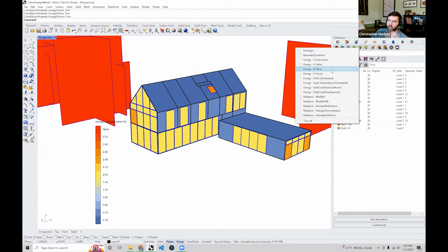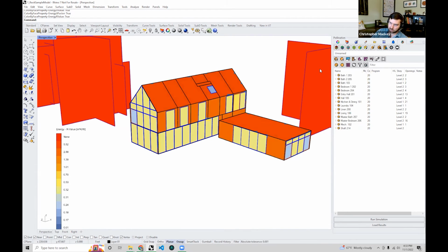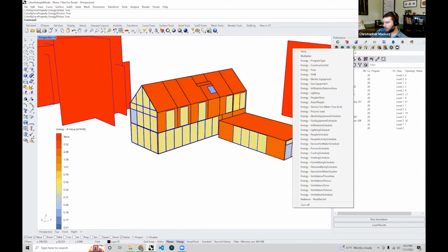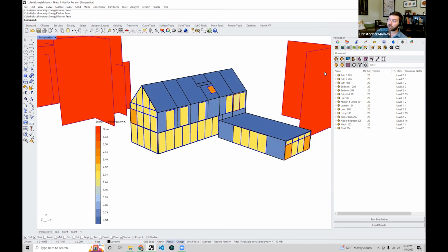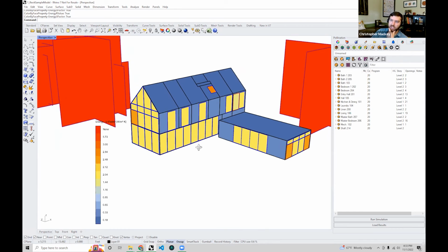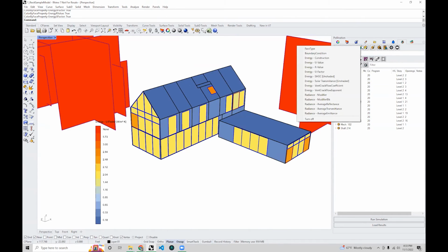I know in the US at least, R value tends to be used exclusively for opaque wall assemblies, and it does not include the air films. Whereas U factor, I'm sorry, is what's used for windows, and that includes the air films. But that's basically right. If you see just R value or U value, that means there are no air films. That's great. Thanks. Yeah, no problem.